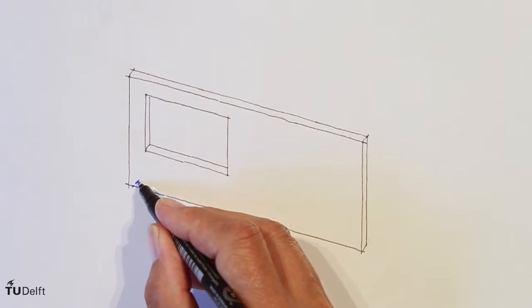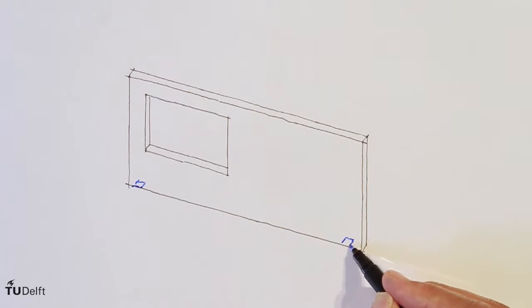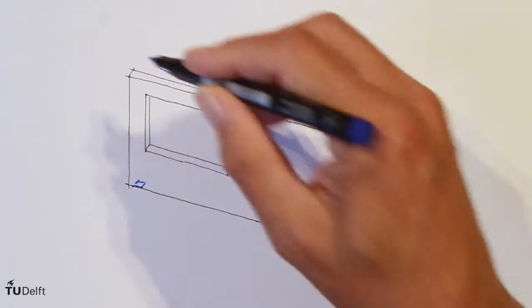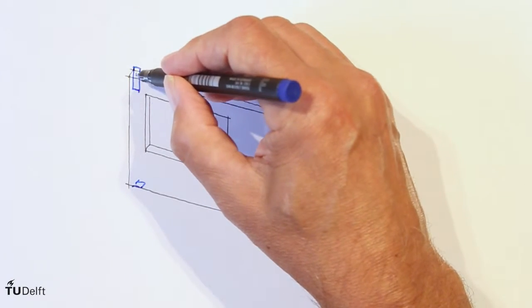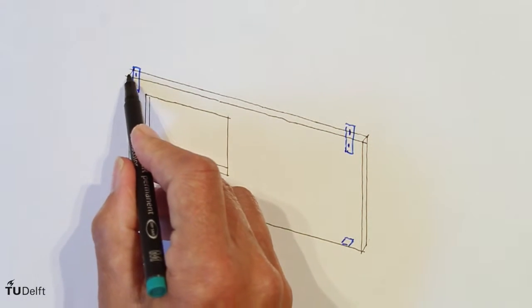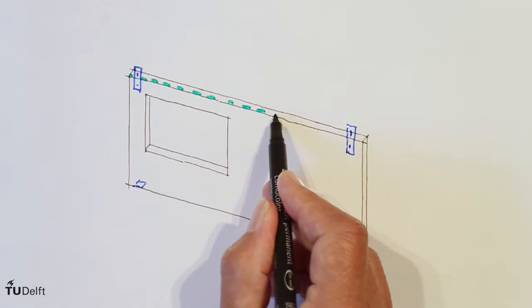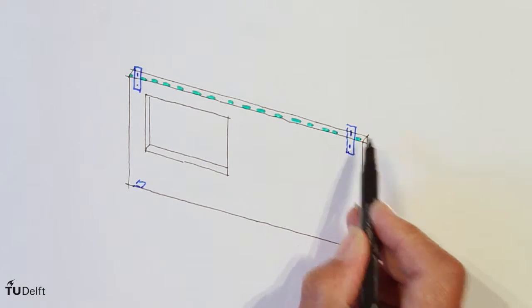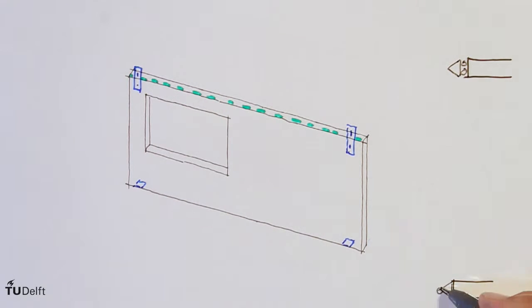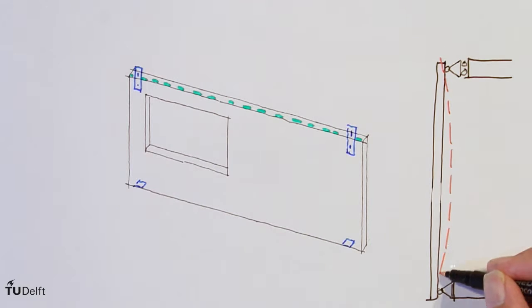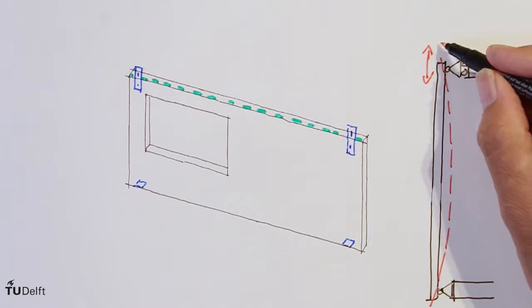The inner layer can also be a plate made from concrete and nowadays also from cross-laminated timber. These elements are fixed on the four corners, bringing their weight via hinge connections to the support at the bottom, while rolling, flexible connections at the top prevent the wall from tumbling over and allowing the floor above to bend freely. The plate can transfer the wind load as a vertical beam to the main construction.